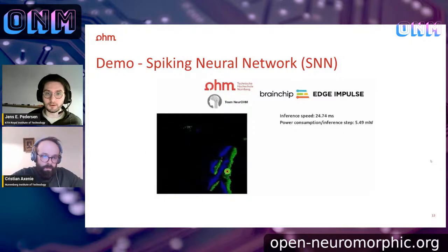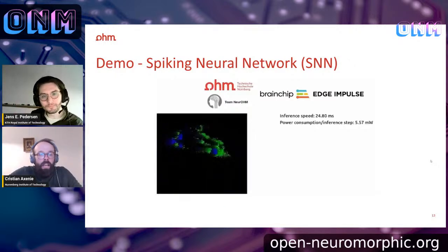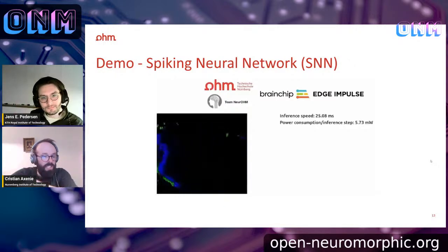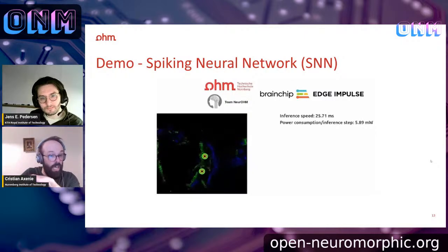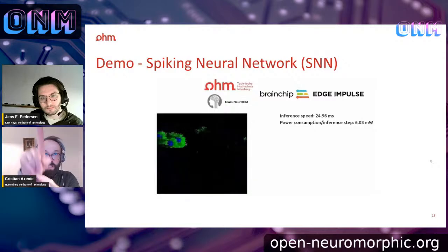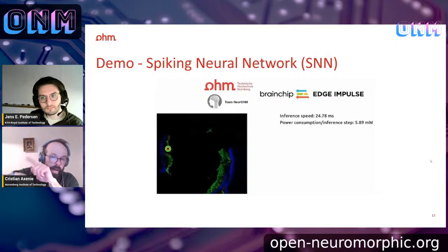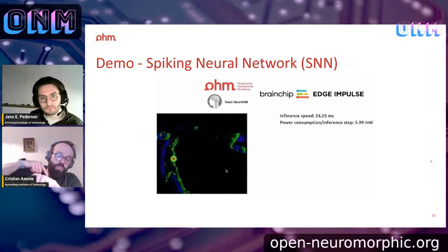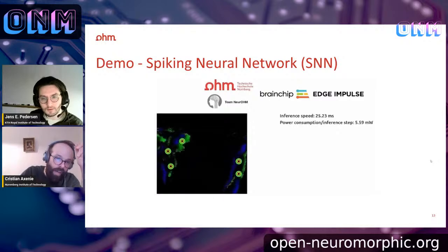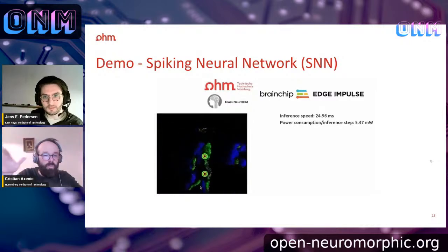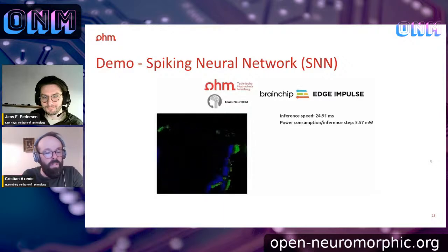If you can get this running in 1.5 hours, then it's just a matter of finding the right model. This is very impressive. The 1.5 hours was Edge Impulse, building the model and configuring it a bit in the web, and then downloading the target for the BrainChip. What you see in this slide is a Flask server running on the Raspberry Pi, getting data from the BrainChip Akida, making this nice window showing where the track points are. So there's a lot of boilerplate around. This I didn't do in 1.5 hours, but took a bit longer with the students.